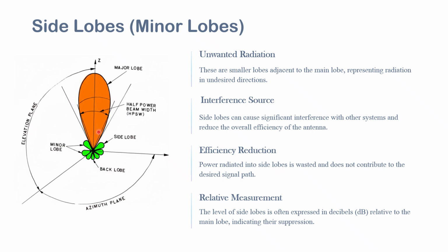In the radiation pattern of the major lobe, you can identify the beam width by taking a 3 dB line with respect to the maximum point, and the angle projected towards the center of the lobe from the 3 dB point will give you the half power beam width. That will be essential for designing an antenna.